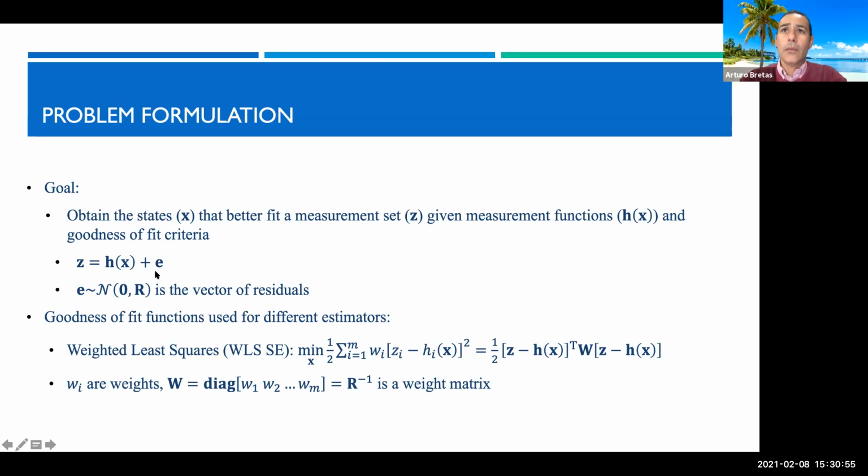And since the physics show that you have several uncertainties related to the measurements, you model these uncertainties, and usually they're modeled as a normal distribution with zero mean and a known covariance. This measurement model you can transform into a weighted least squares approach, considering that the system is over-determined. So you find the best solution by finding the estimation which is the solution of this minimization problem.